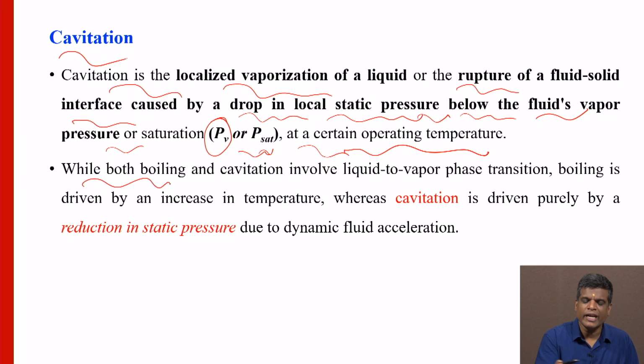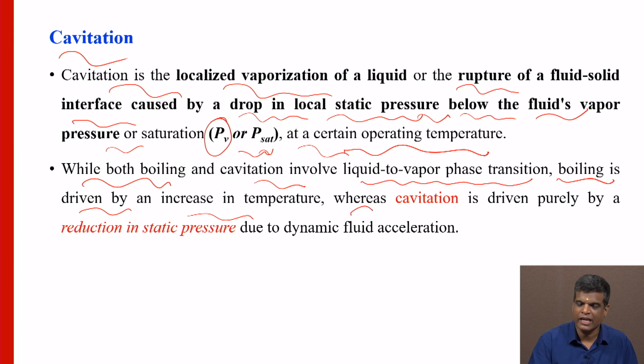While both boiling and cavitation involve the liquid and vapor phase transition, of course we know boiling is driven by an increase in temperature. Whenever you increase the temperature, there will always be boiling, whereas cavitation is driven purely by a reduction in the static pressure due to the dynamics of the fluid.